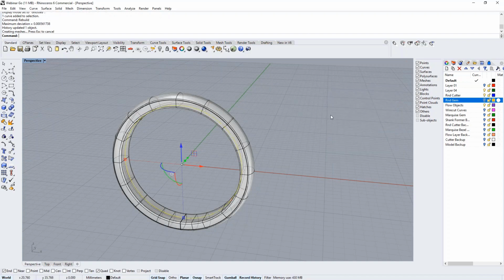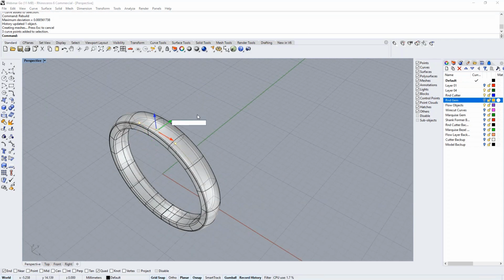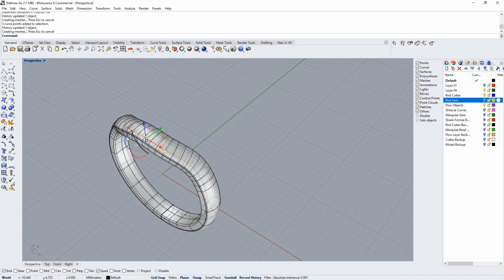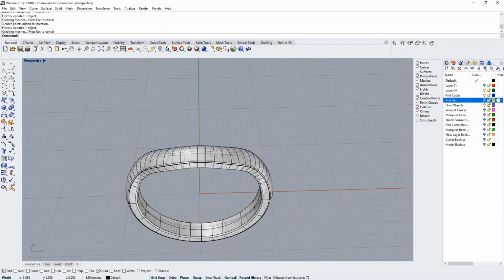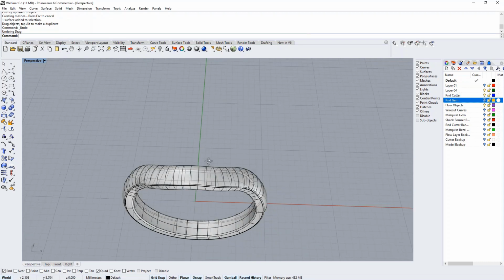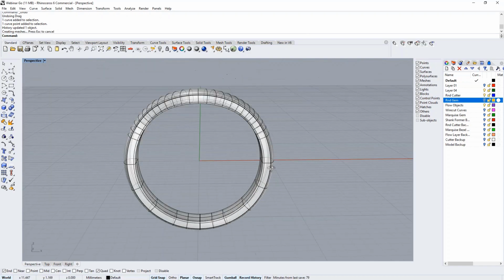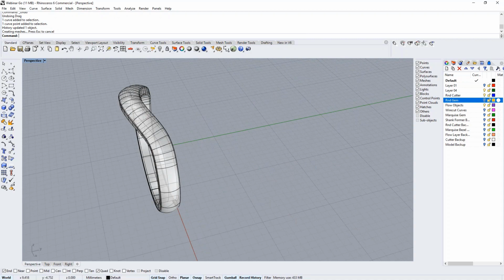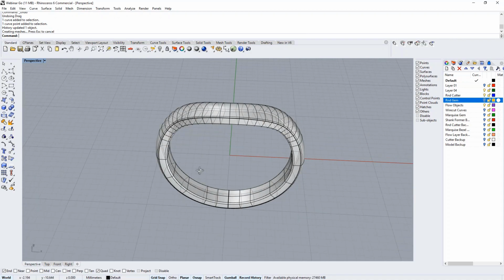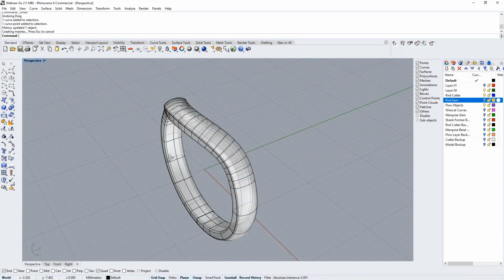So we'll do that. And now I'm going to grab these 3 control points, and I'm going to move them -2 millimeters. And then I'm going to grab this, oops, that's what to do when you make a mistake. Where's my curve again? There we go. And control points show up. I'll grab this one and move it -1. All right. And so you can see how we have a really nice fluid curve, and we've done that with history, and we've rebuilt the curve to accommodate the sort of shape change that we wanted.